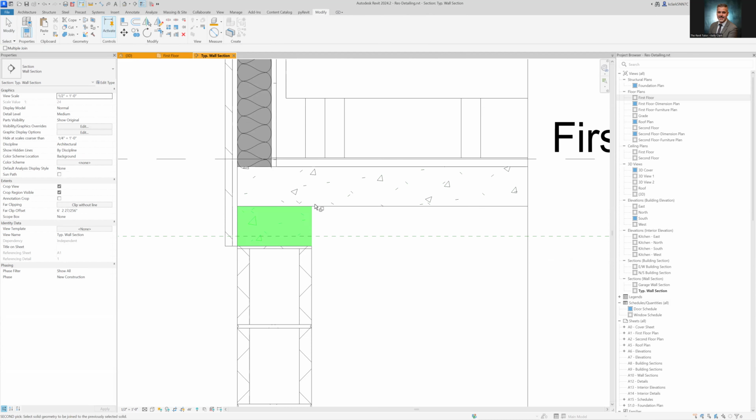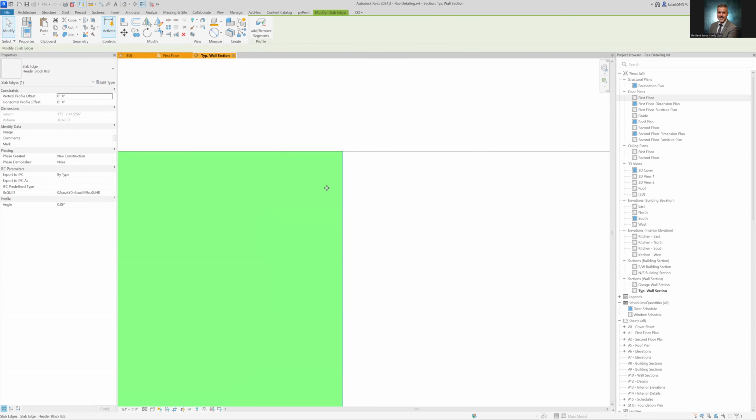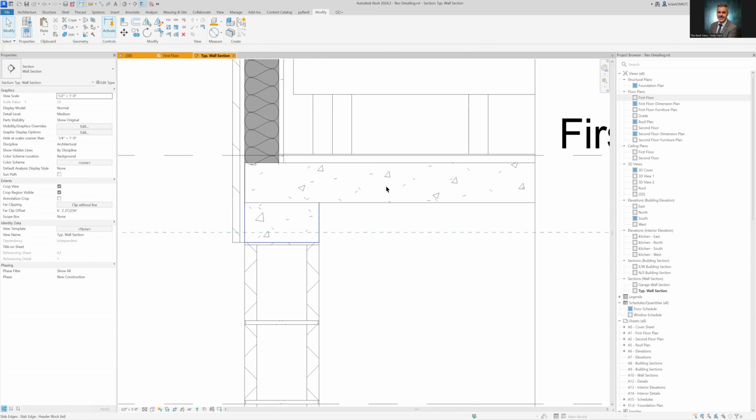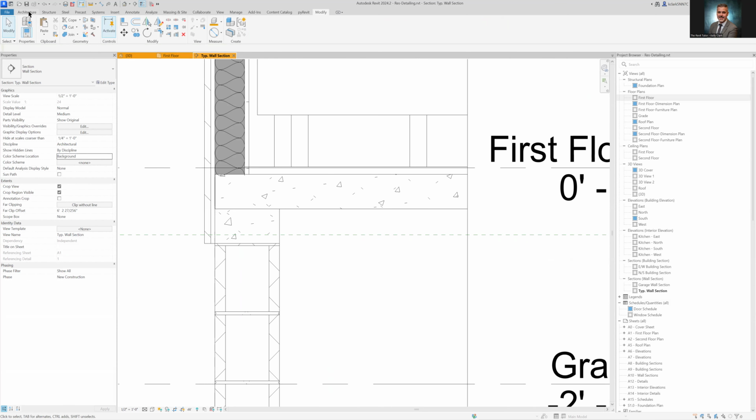All right, so there's probably other reasons too. They could be separated enough by something to create the line. Either way, our intent here is to actually put in a filled region over the top of it, okay? That way I can get that little turn down angle too. And plus I can fill up this little spot right here. So let's go ahead and do that.